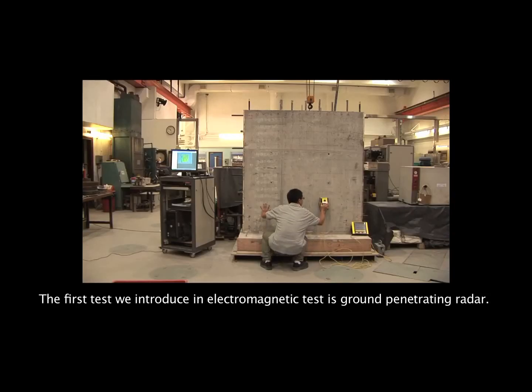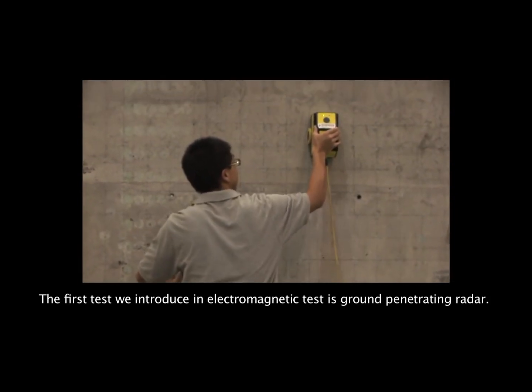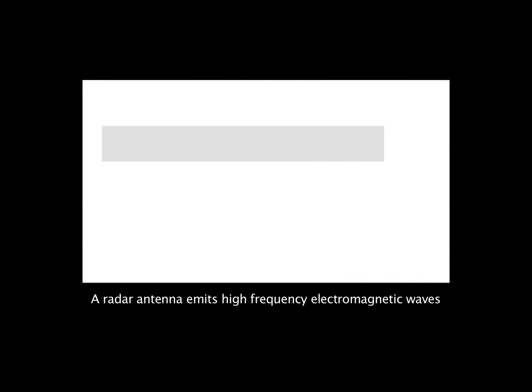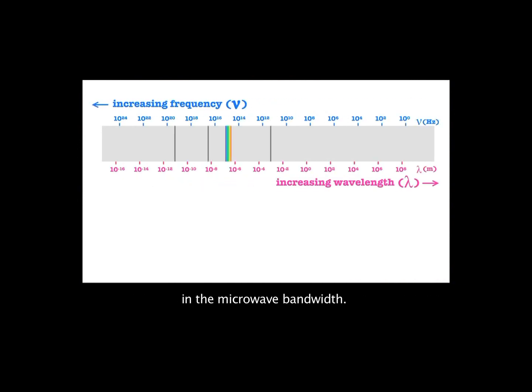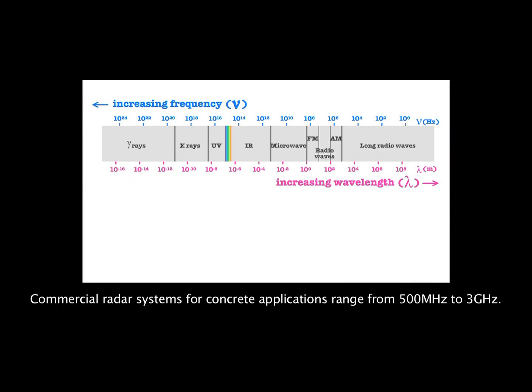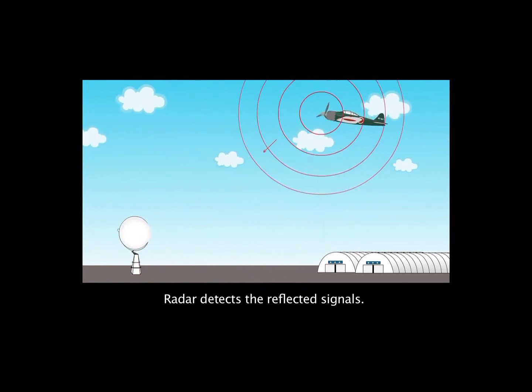The first test we introduce in electromagnetic test is ground penetrating radar. A radar antenna emits high frequency electromagnetic waves in the microwave bandwidth. Commercial radar systems for concrete applications range from 500 MHz to 3 GHz. Radar detects the reflected signals.